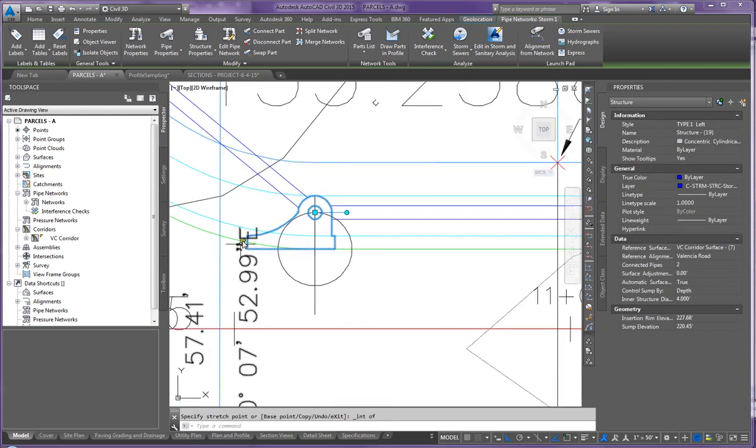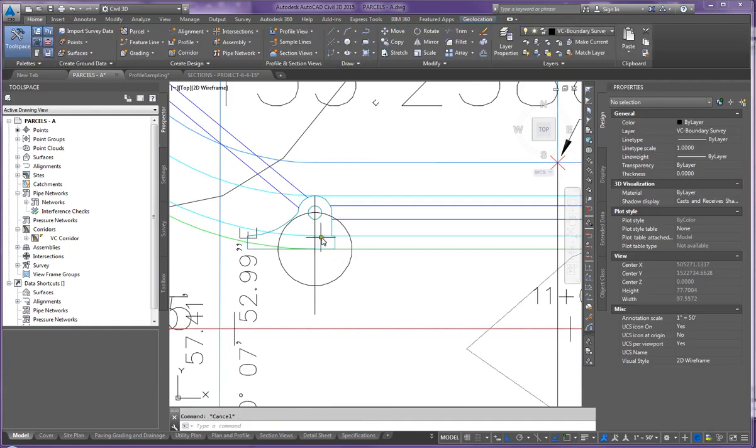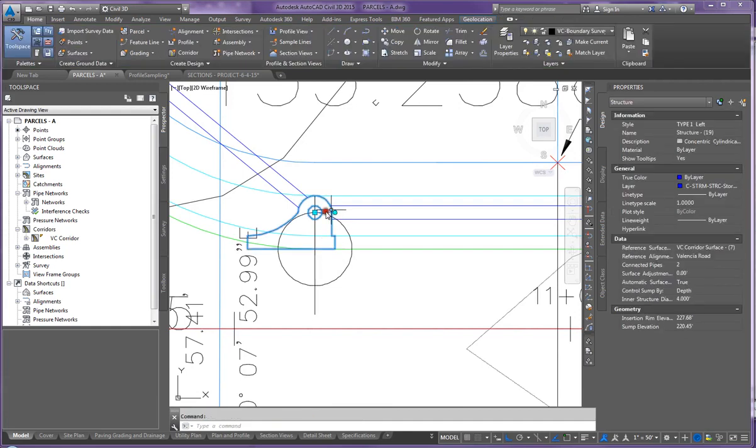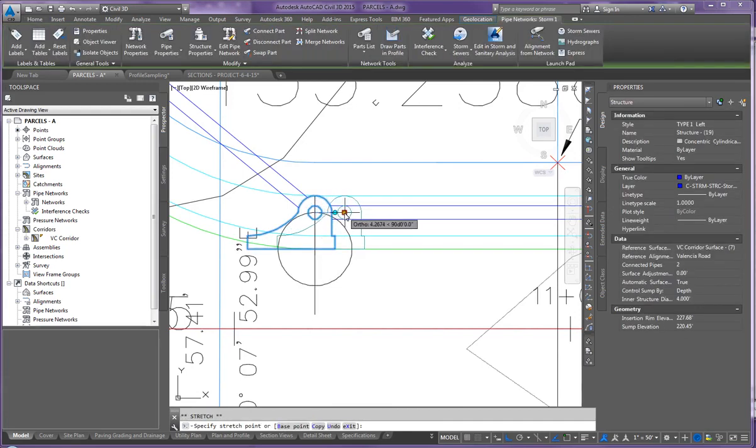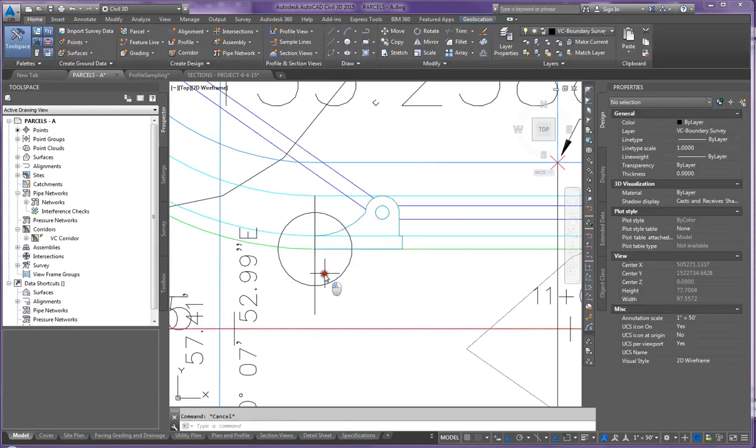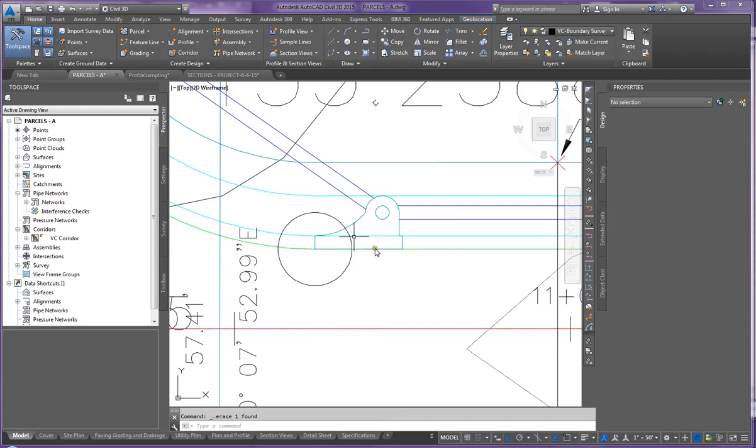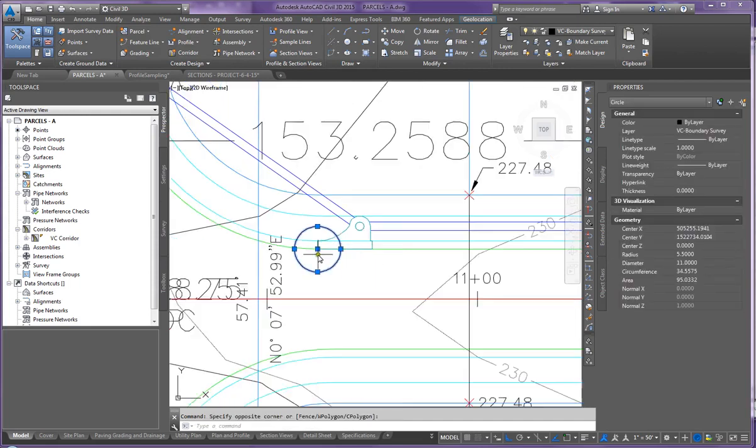Well, see how this hits here? We don't want it there. So we're going to have to pull this back, and I'm just going to eyeball it for right now until it hits here. That's where you need to have that throat start, so you don't have problems when cars turn that angle, they don't break off this invert.